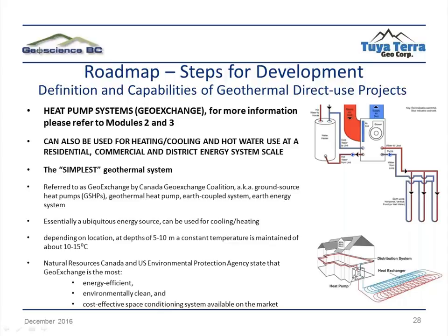And so essentially a Geo Exchange system is the simplest type of geothermal system. For the most part, this geothermal resource at the shallow earth, maybe 5 to 10 meters deep if you're using horizontal loop configurations, or even if you're drilling into, say, 50 or 70 meters deep, this system is not directly utilizing fluids within the earth. So you're extracting the heat from the ground, and you're using a binary fluid that's usually a refrigerant.